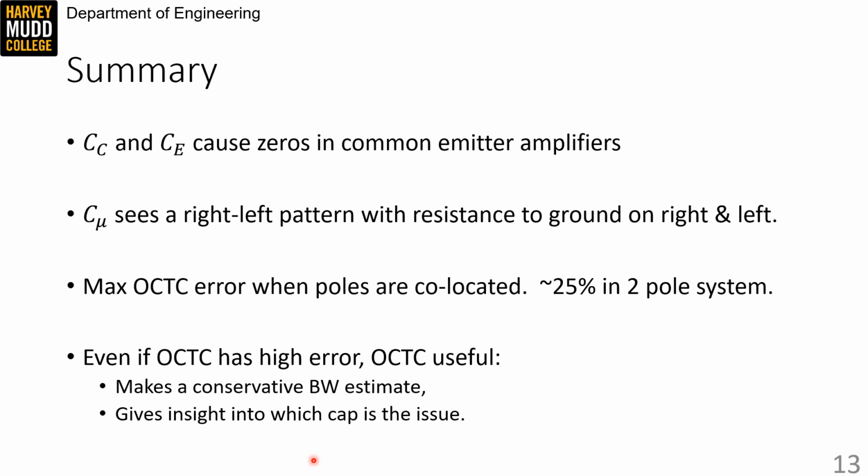But even when open circuit time constant has high error, it's still pretty useful. First, the error isn't that big. Second, it makes a conservative estimate. And third, it gives us insight into what caps are slowing down our amplifier.